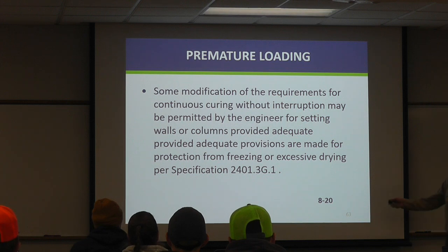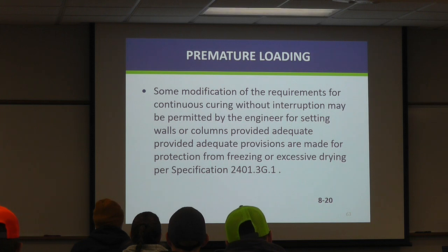So we added a spec a number of years ago to say, so long as you're not going to freeze it or excessively dry it, you can go along and start to tie for your walls or your columns or add forms and so on. But at the end of the day, when they go home, they have to put the curing back on.